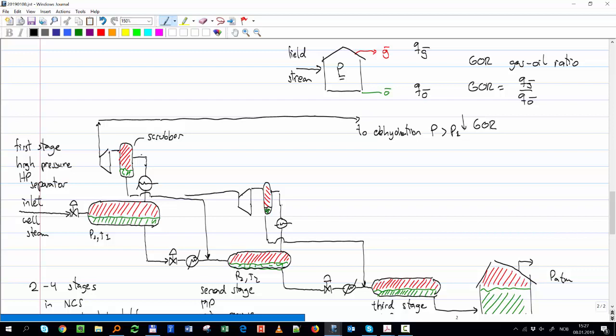Here I have no space, so typically I send it just before the cooler. So I have the cooler here, and I just put it there, such that I do the compression in steps, in smaller delta P steps, and I don't have to invest so much power to go straight from here to here. I do it with a small compressor with small delta P, and then I use this big compressor that will take a higher rate and a smaller delta P.